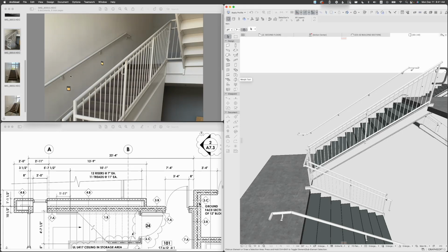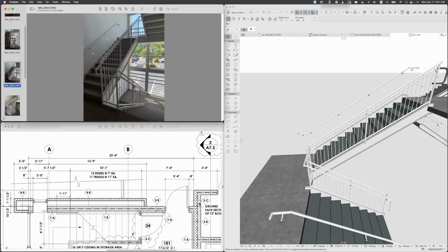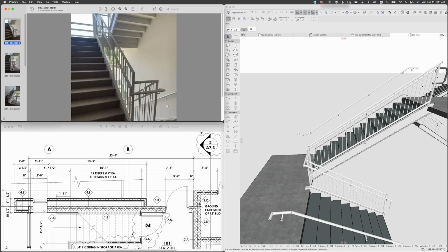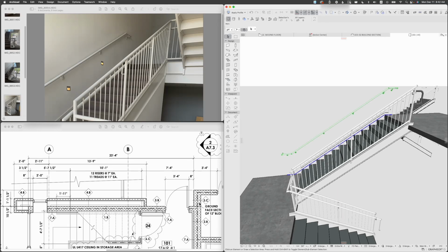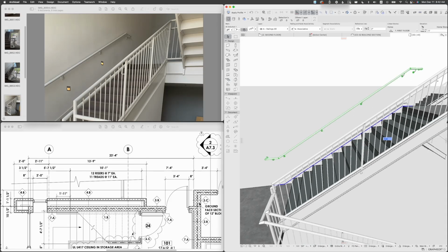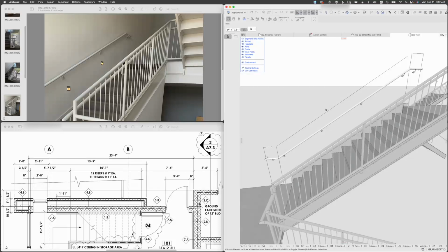That's what we need. Looks like this one only has 4, so it has one at the extension at the top. We can't see from here, but see if I have another picture, but yeah, we can't see that end. But anyway, I'm pretty sure that these two are centered equally, and we have one at each extension. So I would select the handrail and go to edit, select not the top rail, but rather the segment. I have to turn it on.